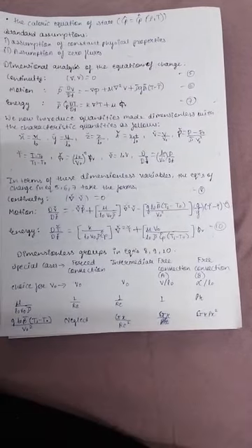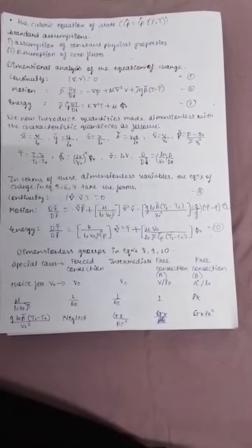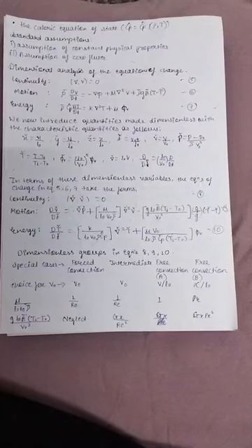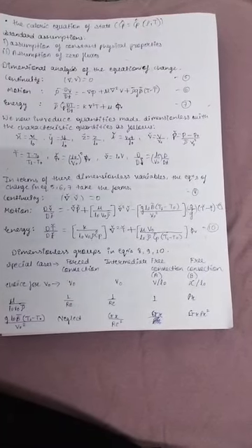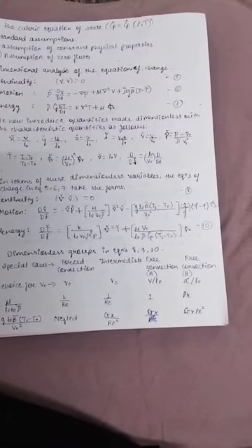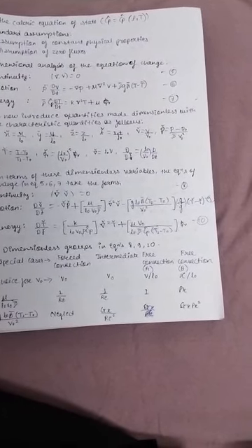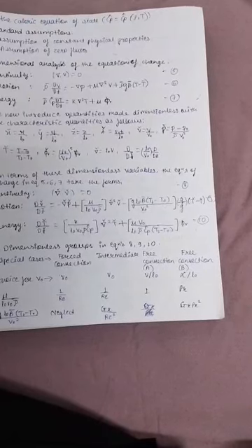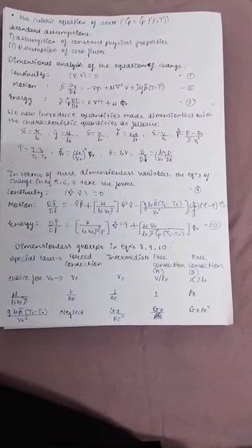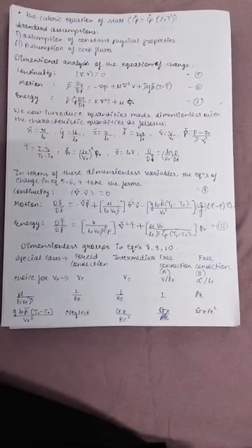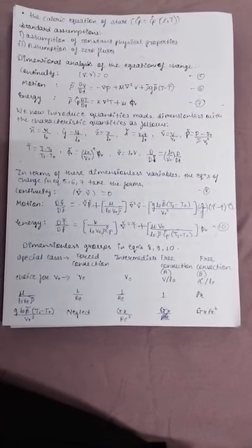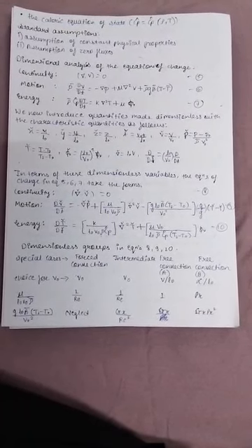We have three regimes: forced convection, intermediate free convection and free convection. Choice for V naught: in forced convection it is V naught itself, in intermediate it is V naught, in free convection case A it is root of nu over L naught, in case B it is root of alpha over L naught.